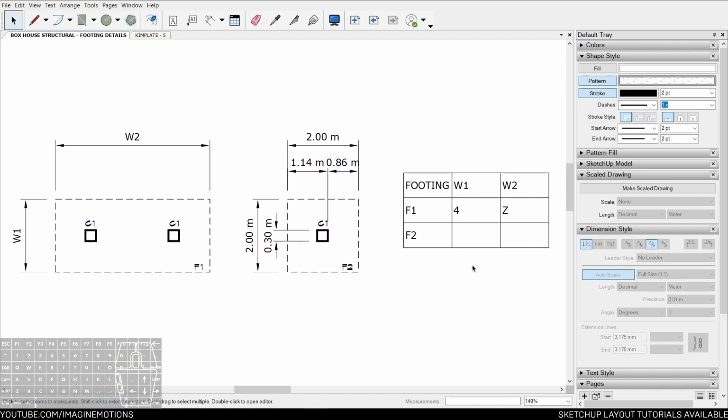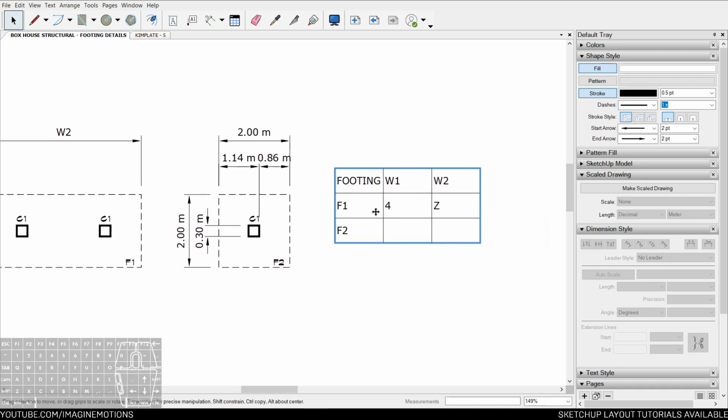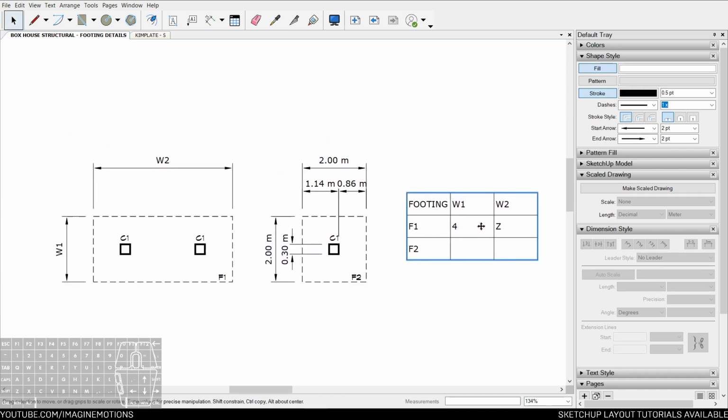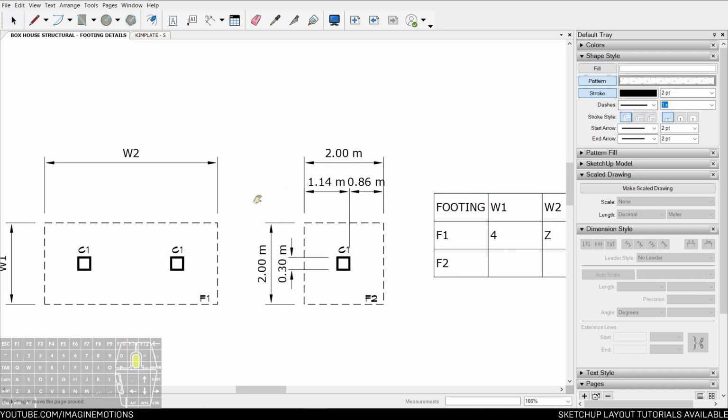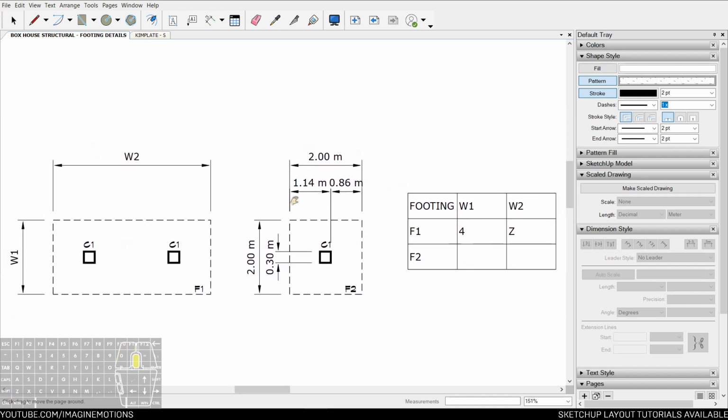This is the use of a schedule. It's like placing a tag, but instead of the tag labeling the drawing, it's a tag labeling the dimension. Like, please see width number 1 over here. That's a call out, but it's a schedule form. You know your calendar schedule? That's why it looks like that. So this schedule actually puts information into this legend W1 and 2. As per technical specification rule, whatever is in the schedule should override what's in the drawing.